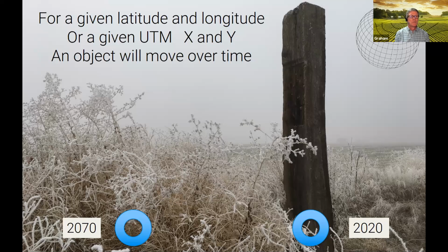Some mathematical modeling systems, for example, the North American Datum, NAD, which produces the state plane coordinates, have fixed points in time. And that's an example: if you try and merge information coming from state plane coordinates with a download from Google Earth, then it's likely they won't match up. And Jo was going to cover importing things from different datums in the presentation on Monday.